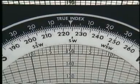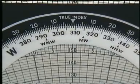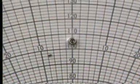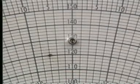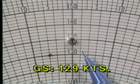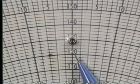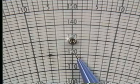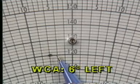Now rotate the azimuth until the true course of 310 degrees is under the true index. Then slide the grid until the wind dot is over the true airspeed of 120 knots. Your ground speed can now be read under the grommet. In this case, it is 129 knots. You can then determine the wind correction angle by counting the number of degrees the wind dot is located from the center line. In this case, each line represents 2 degrees, so the wind correction angle is 6 degrees left.